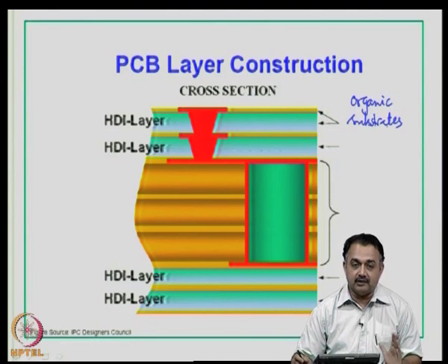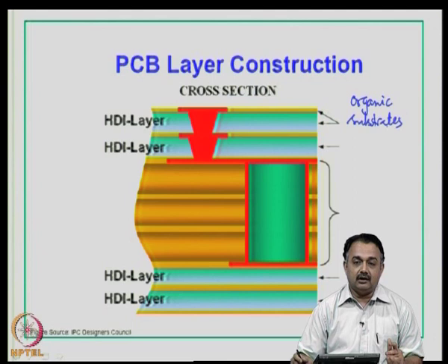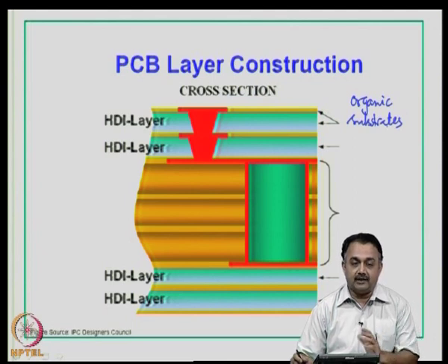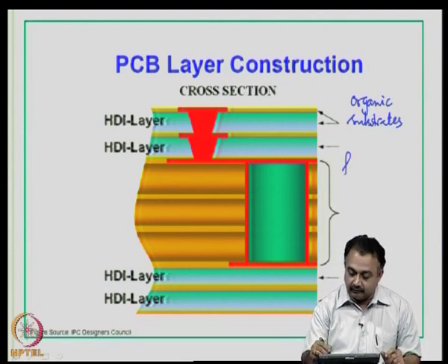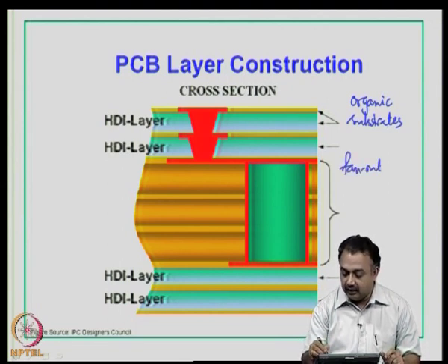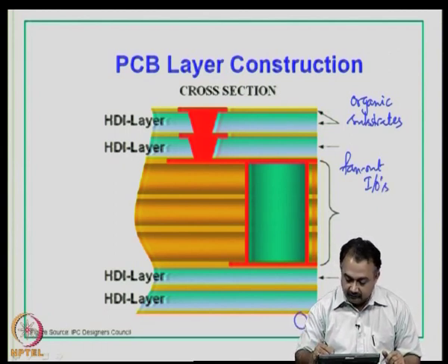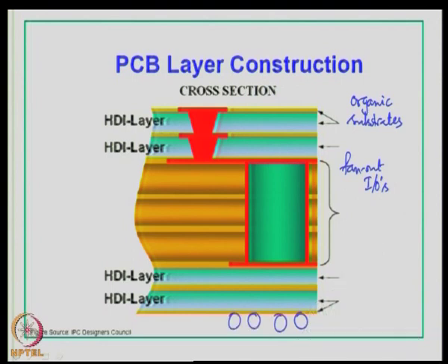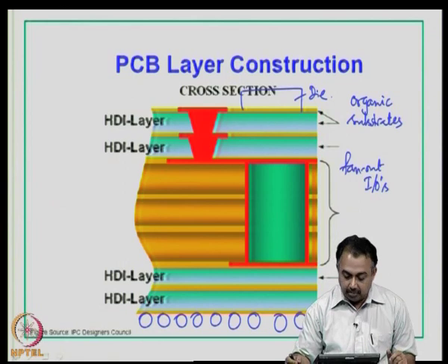It is similar to a PCB configuration, but here in a package substrate, you will look at basically fan out of the IOs from the die to this particular package, and then finally, you might end up with solder balls. If this is the cross section of a package, you might have a die here, and this is the configuration of the package.